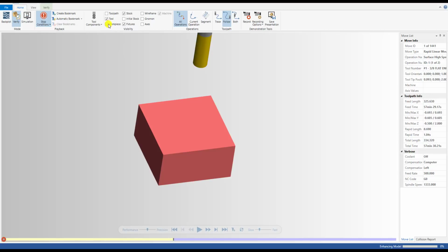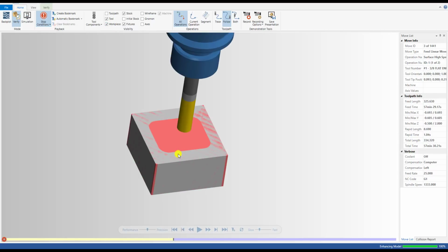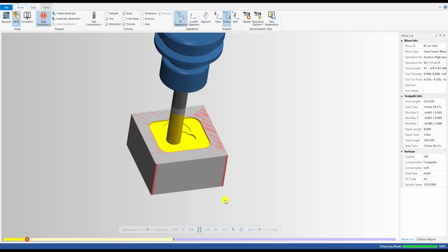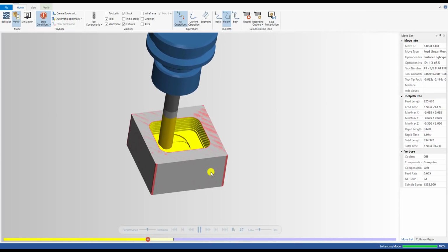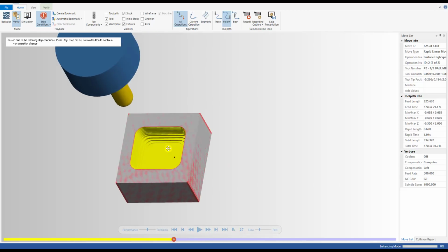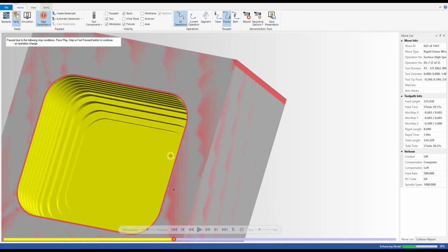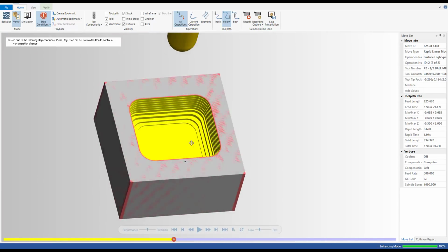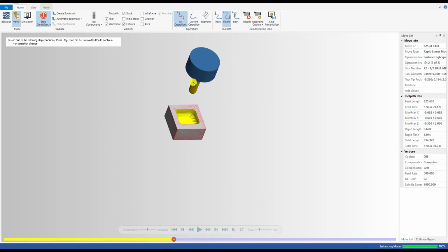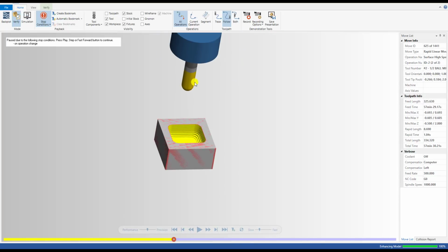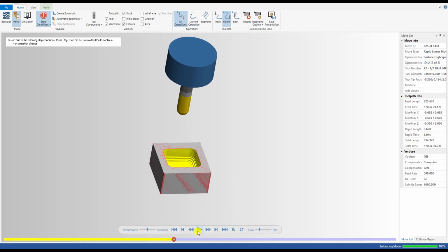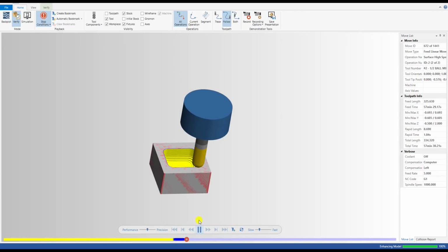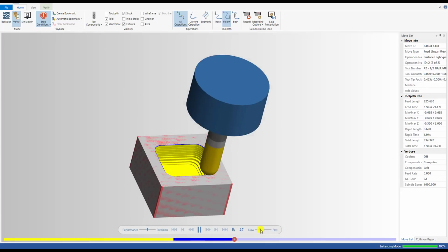You can see this is our stock and this is the workpiece, and now this is the tool after it's running the roughing operation. I use a flat 10mm so you can easily see the problem. Okay, and on the screen this is the part after the roughing operation. And now here's the finish tool. You remember what this is? A 1/2 inch ball mill, so the radius here is a little bit bigger than the radius on the part. And now I try to run this. You can see it's running smooth.